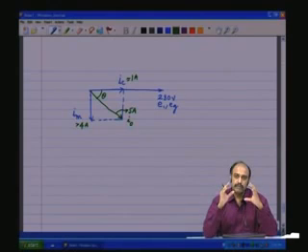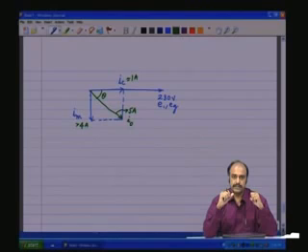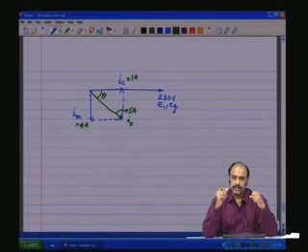So, there is only a portion of the flux that actually links between the two coils, and that is called the mutual flux. So, we have the leakage flux and the mutual flux, which results in actually lesser voltage being developed across the other windings in the core.